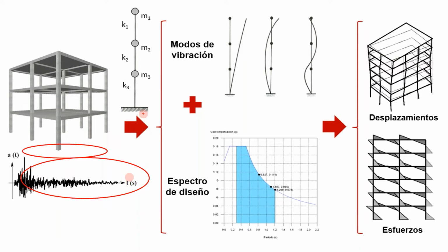One thing that I almost forgot is that we also have the acceleration of vibration mode of the software in 3 ways. One, we can choose the code. The second one, we choose the percentage of mass we're going to excite in the building, and it goes from 90% to 100%. And the last is something that we call by user, which by default has a number of 6, but we are considering only 3: X, Y, and 1 rotation.